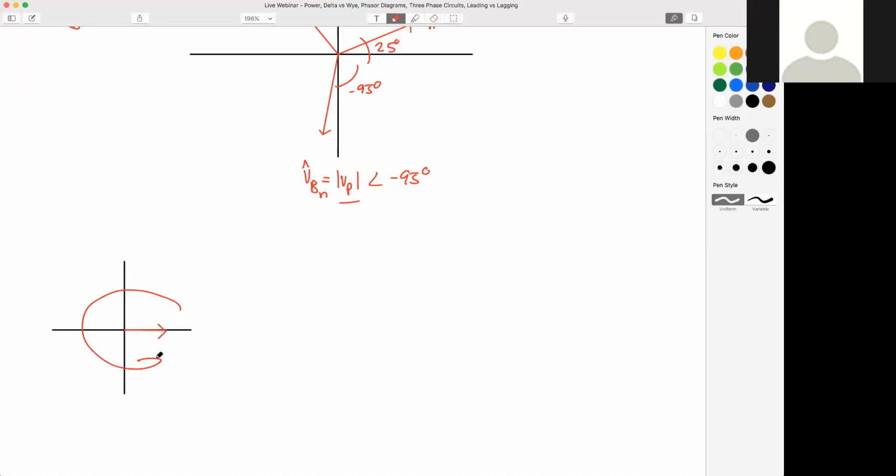Remember, our phases are always rotating with respect to time, or where they're at in the cycle. Anytime we analyze relationships, we get to choose what snapshot in time that is. And typically, we want to choose it when our phase voltage angle is equal to 0. So I'm going to say this is VAN, with the same phase voltage magnitude. This time he's got an angle of 0.